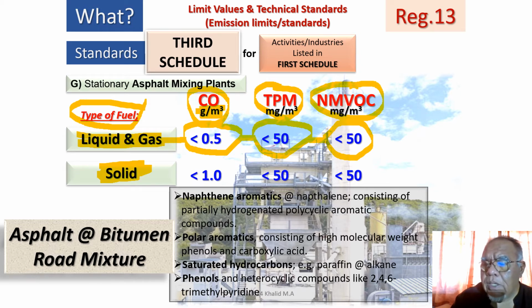But despite using light fuel oil and medium fuel oil, if your feeding is good, multiple nozzle feeding, and you can maintain a higher temperature, enough to adjust the air fuel ratio to a level where you got almost complete combustion, you can bring down the carbon monoxide. Definitely, those who are operating these machines know much better than I do. Mechanical engineers, you know this better than I do.